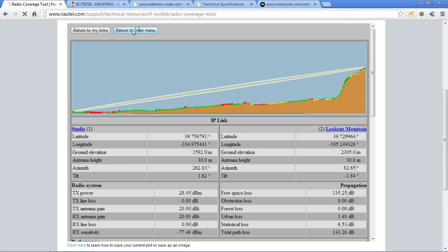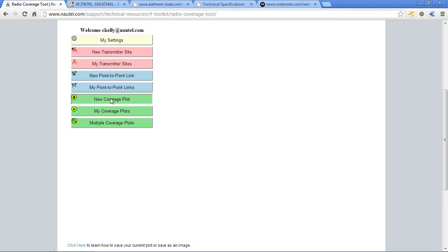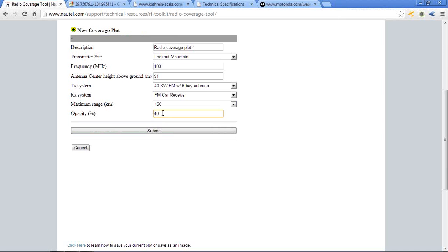That's the transparency of the coverage. Okay. The way it works is in Google Maps, the map background that we use. Yep. The opacity of the image depends on that value. And it's a limitation of Google Maps. Your image has to be already transparent to be shown transparent in Google Maps. So if it was 100%, you would not see the underlying map, and if it was 0%, you couldn't see the actual plot. Yeah, it will be opaque at 100 and completely invisible at 0. But if you export as we did before with the zip file, you don't have this limitation in Google Earth. You can change the transparency there, because it's just an overlay at that point.